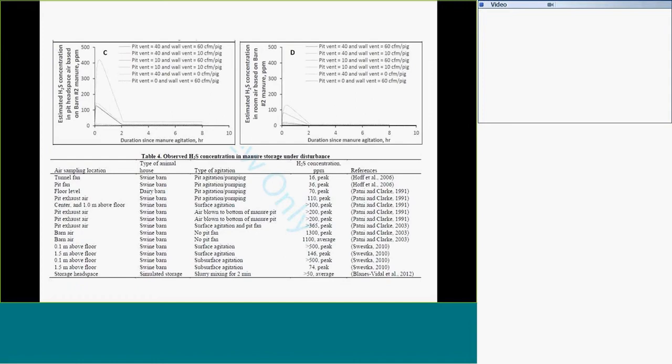It's called IDLH, immediately dangerous to life and health concentration, 100 ppm. And in the room, when the ventilation is low, it exceeds 100 ppm. Dangerous situation. The results kind of support the literature studies. This data is from a paper I submitted to ASABE. You can see in a lot of cases the concentration is 500 ppm, 1000 ppm, not to mention 100.